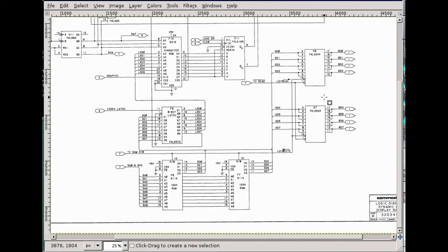So if there is a fault on these two signals, the enable of these two bus transceivers, then it may happen that some part of the data bus activity from the CPU is leaking to the screen data bus part, even when it's not supposed to be connected, and trash the whole screen.